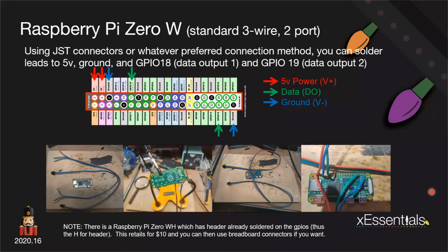Yeah, I would not cut those down, because usually those are the way the PCBs are wired that are actually holding the pixels. If you try to cut a row off, then you're going to orphan the rest. You'll have one row that'll work, and you'll orphan all the other rows.